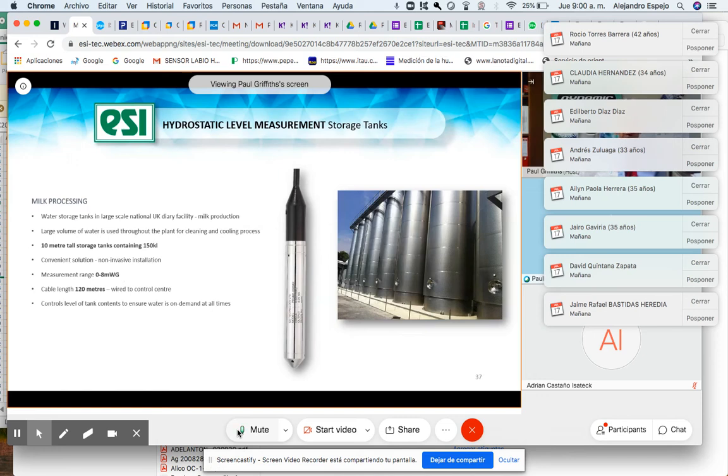We are in the process of re-evaluating the product range, and we know that we need a hygienic cable. So we're looking at modifying the back end here, where the molding is on this one. We're looking at having a different system so that we can use FEP cable, which is a good cable for food and also for chemicals as well.